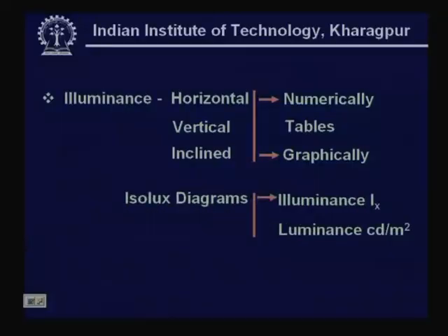So, this is where our fundamental understanding of the light output and illuminance levels obtained based on the source needs to be taken, which normally, based on these relationships, the manufacturers provide in their catalog in the form of numerical values, in the form of tables, graphically in the form of what we call diagrams.